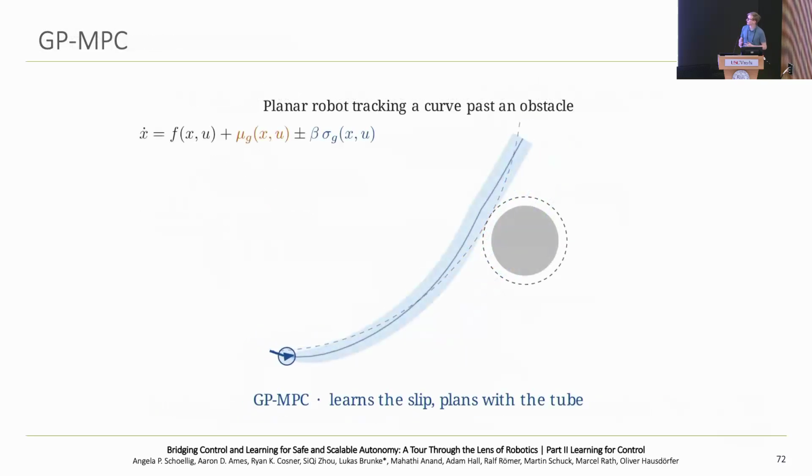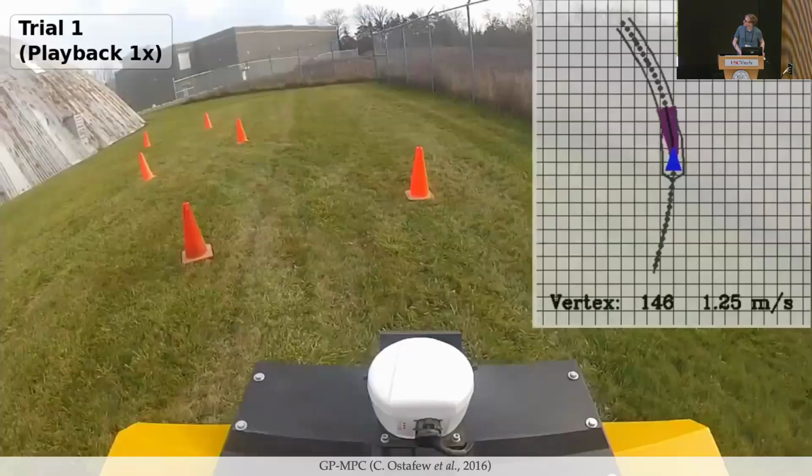And so now we can come back to our initial example. Now that we have this uncertainty, that also gives us a way to understand how uncertain we are about the prediction horizon. We can now use this model in our controller to roll out our dynamics and predict with this uncertainty from data. And so you can see that this is much less conservative than what we had before. And so actually we can track the reference very nicely. So we stay clear from the obstacle.